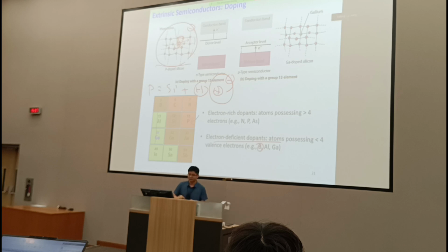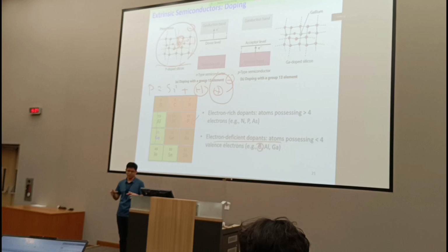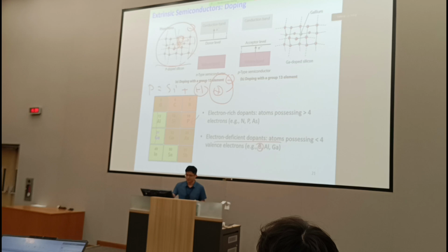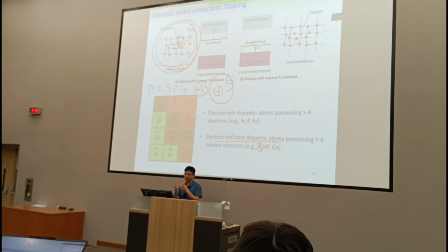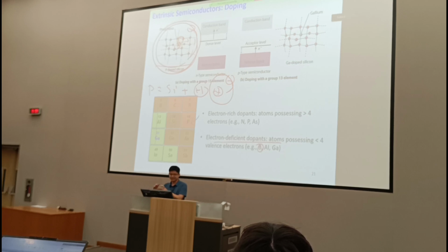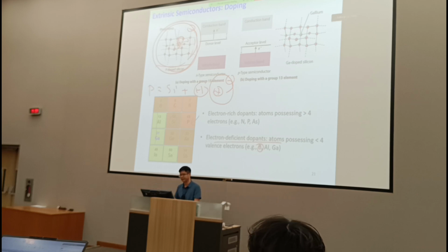But here the difference is that the electron is living inside a solid, right? There are so many nuclei nearby that can cause screening. That's why these electrons are loosely bound to the impurity center. The impurity has an attractive force, so if you give a little bit of energy, these electrons escape. Once it escapes, it becomes a free carrier, and this causes ionization. That's the way to increase the electron concentration inside the semiconductor. That's the process of ionization of dopants. Okay.